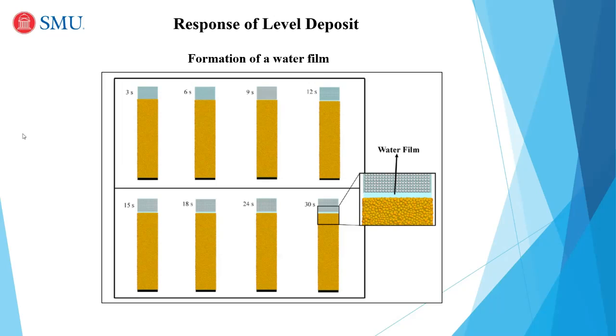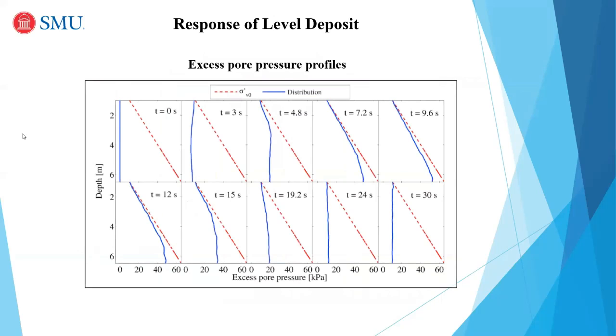Your soil, anything there now, is not really being founded on grains. It's founded on water. It's supported by water. And the interesting thing about these results, this is the effective stress profile, the red line, and you notice it starts on the top with a value of 10, which is the magnitude of the imposed crust stress. As pore pressure builds up, it picks up these 10. So water is carrying the weight of this crust, and that continues during shaking and post shaking.